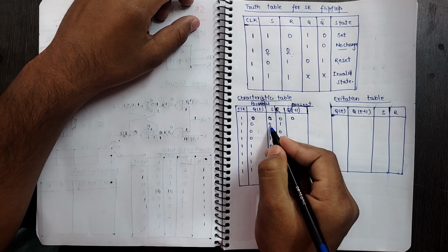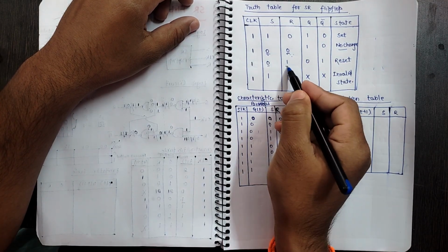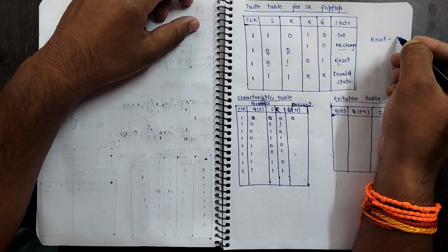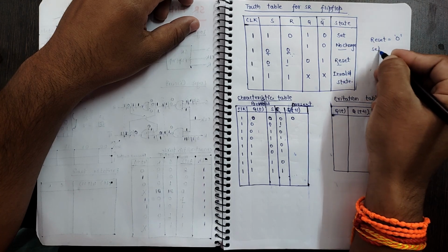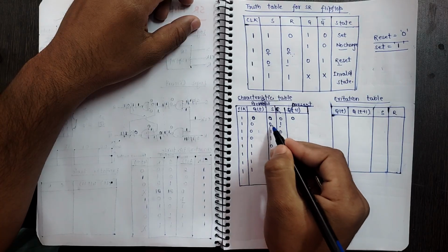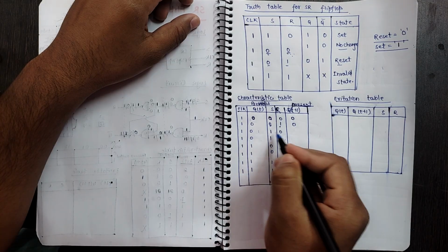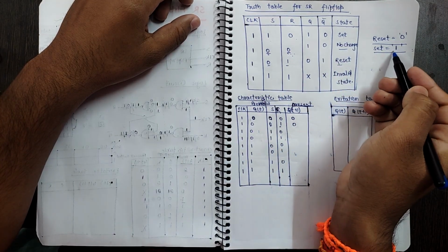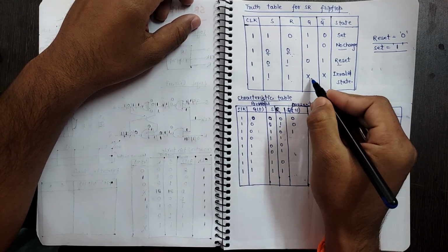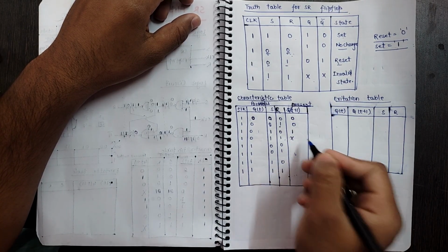Now we will match this 0 and 1 value in the truth table. Where can we find 0 and 1 as S and R? Here, this is called reset. Always remember that whenever reset is given, we write 0 as it is. As a trick, for set we write 1. So for 0 and 1 we get reset, which we can write directly as 0. When 1 and 0 is there, set means 1. Similarly, when we get 1 and 1, this is a don't care, an invalid state, so we write it as invalid state or don't care.